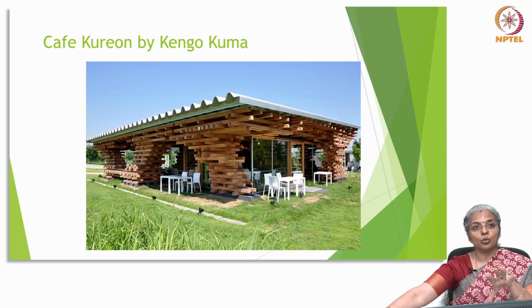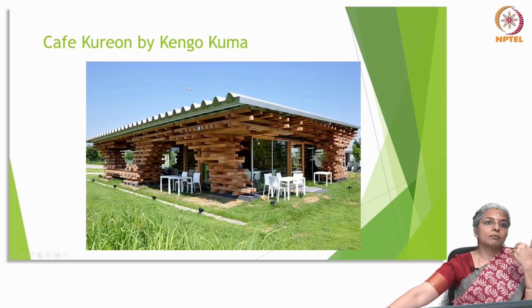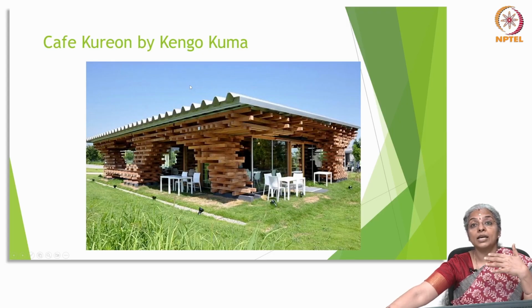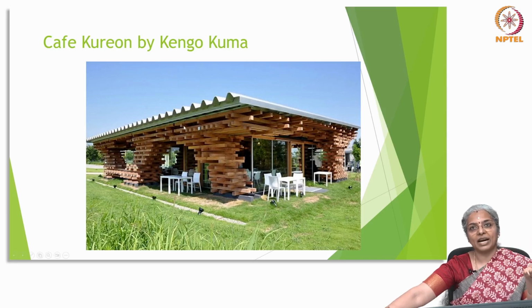All you can do is detach this building easily, because all joints are seen clearly, visibly, and it is more a mass supporting mass kind of a system, because of which the building is standing, and it is not like the building is held together by a major jointing system. It is not like that, and therefore this building is easy to dismantle.